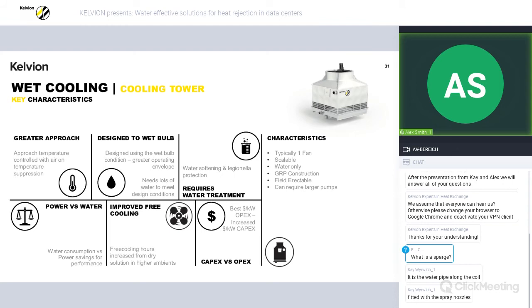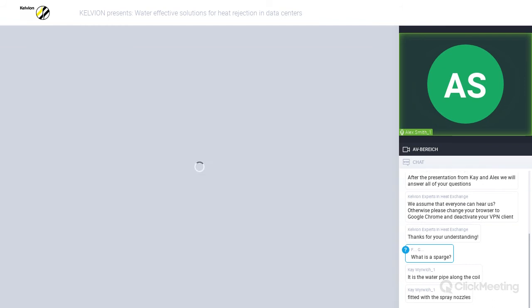Cooling towers are often subject to many health and safety regulations and can require routine inspections to ensure proper maintenance has been upheld, due to potential health risks caused by retention of water. Whereas a padded system or a spray system can have self-draining qualities which minimize this risk.